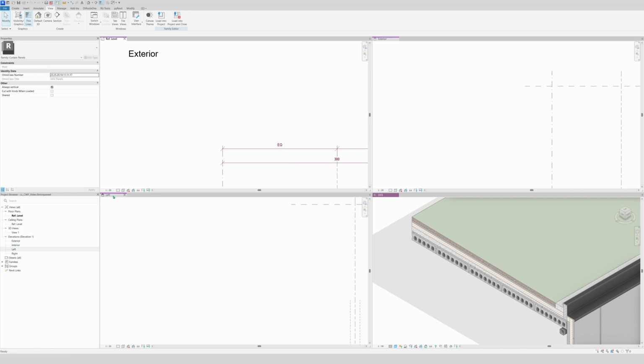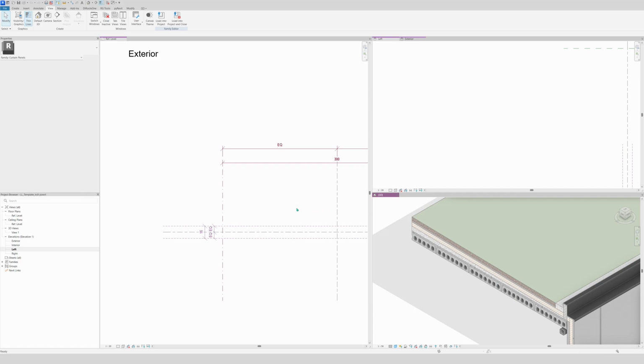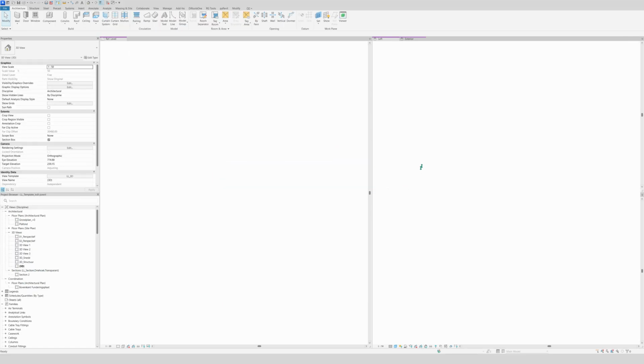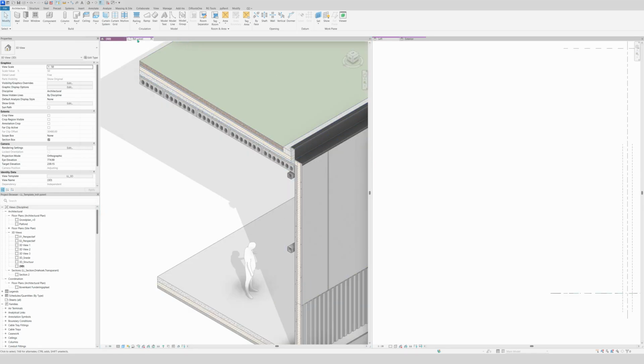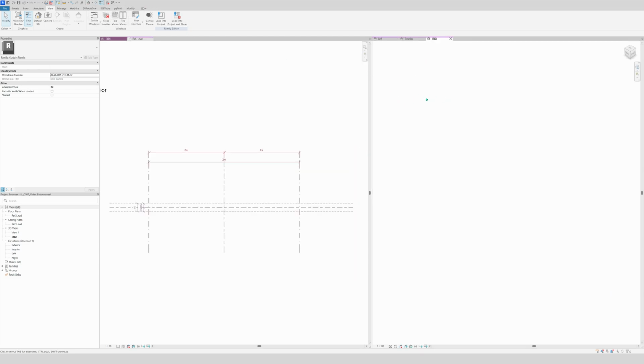So we will do left and exterior with this one, and this 3D model, we don't need it at the moment, so we will move it right here with this one. Voila, and click on a reference line. So that's our side that we need. And right here I will click on it and use a 3D. You don't see much at the moment because we didn't draw anything.